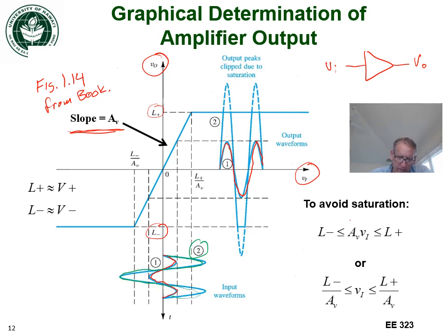And what you notice is that would create a large enough output that the amplifier can't create a high enough voltage given how large the input is. So the signal would go up and get cut off, or clipped as they call it, on the positive half and also on the negative part of the waveform. So this would result in clipping or distortion.